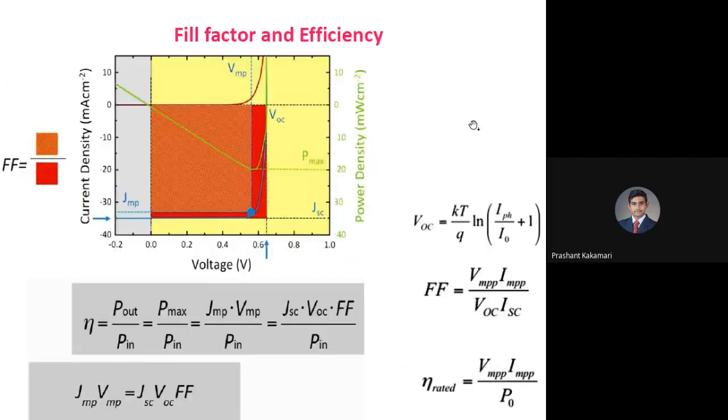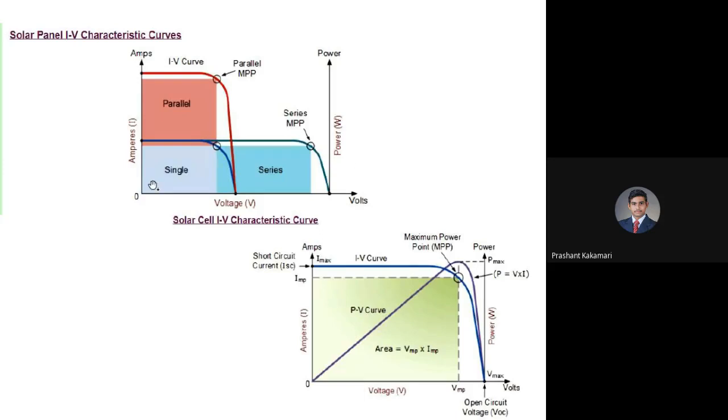Similarly, in this graph, it is explained that as you go on connecting the solar cells in series, I can improve the voltage, because for the heavy devices or the very big machines, the voltage required for running the machines is very high. But compared to the other applications with very low voltage, we need only current, maybe high current or low current, whatever, with low voltage. Okay. So if you connect the solar cells in parallel, what will happen? You can increase the current, not the voltage. So it all depends on the application.